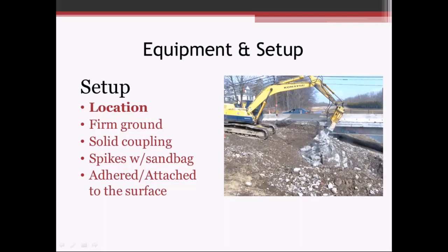Maybe that's the structure that we're trying to protect from construction vibrations once they start driving some piles here for the abutment or something like that. So to set up near this hole ram is really not practical. We want to set up near this house because we want to see what kind of vibrations that structure is seeing, and we want to make sure that we're controlling those adequately. We want to make sure that it's set on firm ground. You've got a good solid coupling.